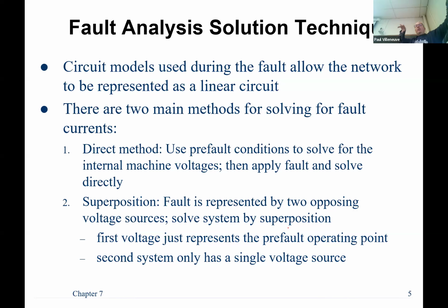You have generators all over the place. So you think, okay, a generator over here is going to have a lot of fault current. But what about a location that has 7 generators plus this generator feeding fault current? Is that possibly higher? You can't guarantee that that's the case, and you can't take chances here, right? You can't say, well, I know that that has to be the highest fault current, so have a good life for everybody else. You're like, no, you got to prove that that's the case.